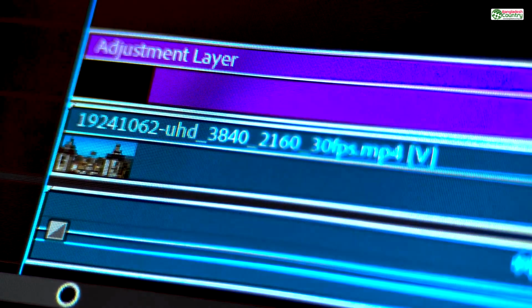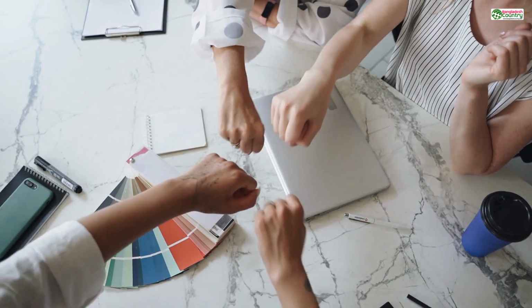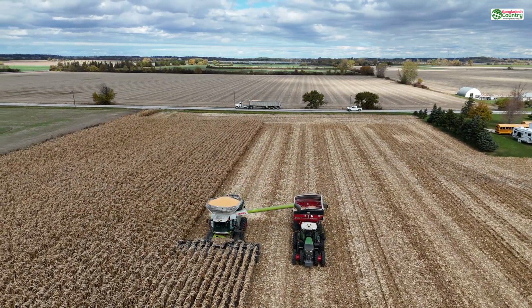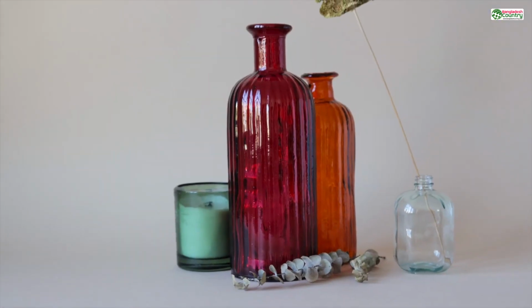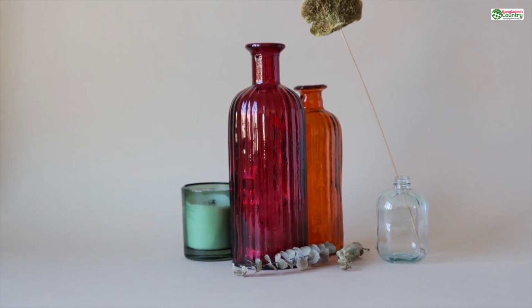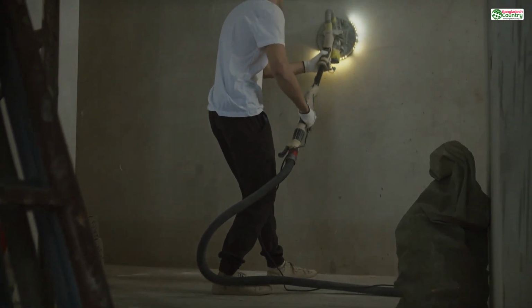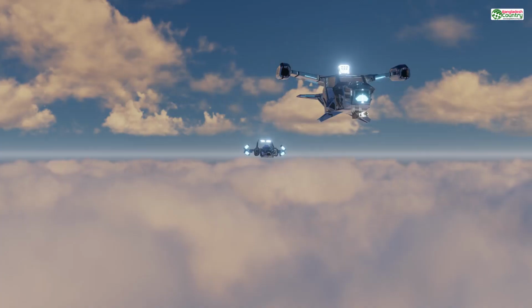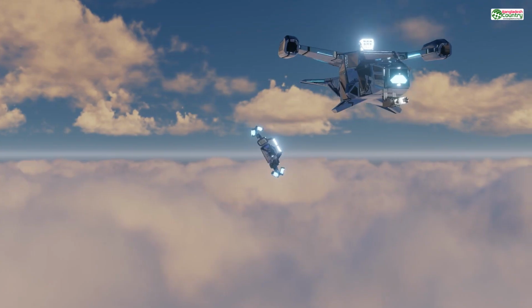So, how do you put this all together? You combine percentage and pattern to engineer the soul of your part. A decorative vase might be perfect with 15% lines infill, fast, cheap, and just supportive enough. A wall-mounted tool holder might need 40% grid infill for good, reliable strength. And that critical drone arm that cannot fail? You might choose 70% gyroid infill to give it maximum, multi-directional strength and impact resistance.